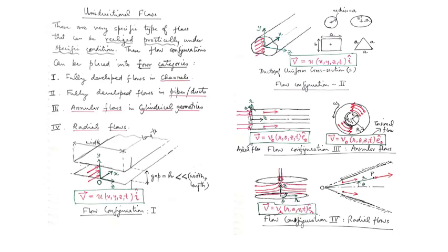but you can have a single cylinder which is immersed inside a liquid and is imparted rotation. The fluid outside will also develop a purely torsional unidirectional flow. Similar is the case with liquid filled inside a cylindrical container, with the cylinder being imparted rotation. The fluid inside will again develop a torsional unidirectional flow. Now coming to the last category, which is the radial flows.